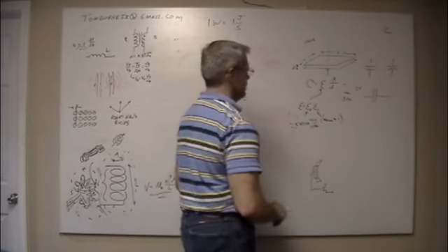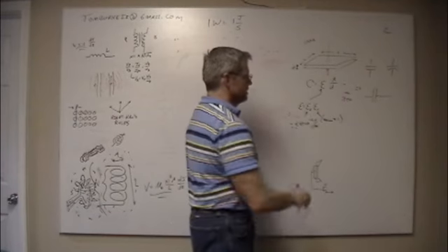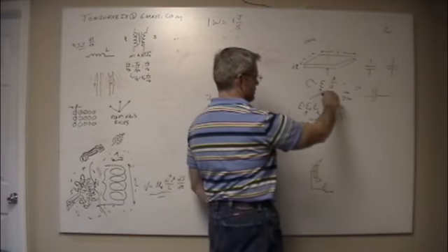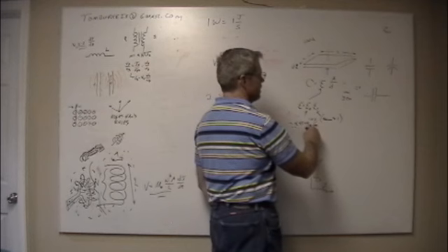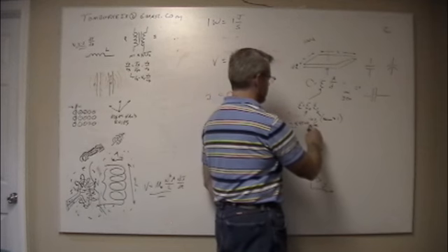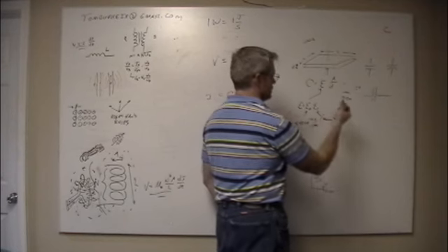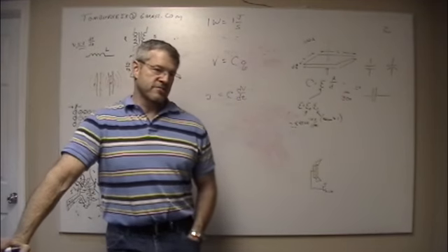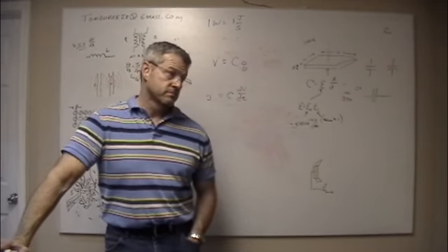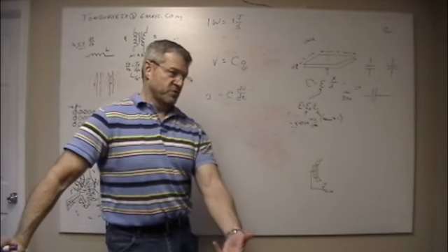And if epsilon, if you're using glass, that's a pretty low number, but already this number's big, and even though this number's small, even if that's still minus 12, that's 300. Take 3 off of there, that becomes 24. It's 24 nanofarads. A decent sized capacitor on circuit boards is in microfarads. Yeah, it's only... that's pretty big.